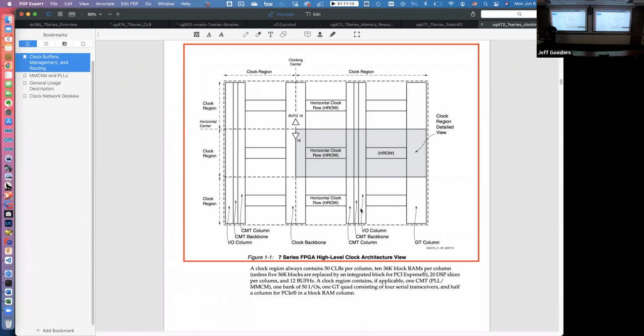If you're going to run at maximum speed, you just can't bring in a clock on an arbitrary pin, run it through programmable routing to all the flip-flops in the design, and expect a design that has any hope of working. If you take 620 from Dr. Worthland, I believe he talks about clock skew. The idea is you want every flip-flop in the entire circuit to see the clock edge as close to the same instant in time as possible.